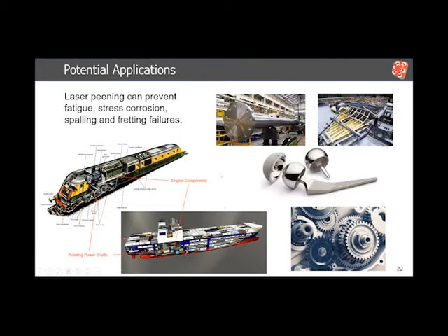We've already generally talked about transportation, but things like crankshafts, I think it was Michael Coutura who talked about crankshafts today. Being able to engineer residual stresses on crankshafts, which is a component that's been around for well over 100 years, is an important capability of extending that. So if you're going to design a new engine to go in a locomotive, for example, being able to apply engineered residual stresses to that part to remove some of the weight so that it becomes a more efficient system is a way to begin to look at those.